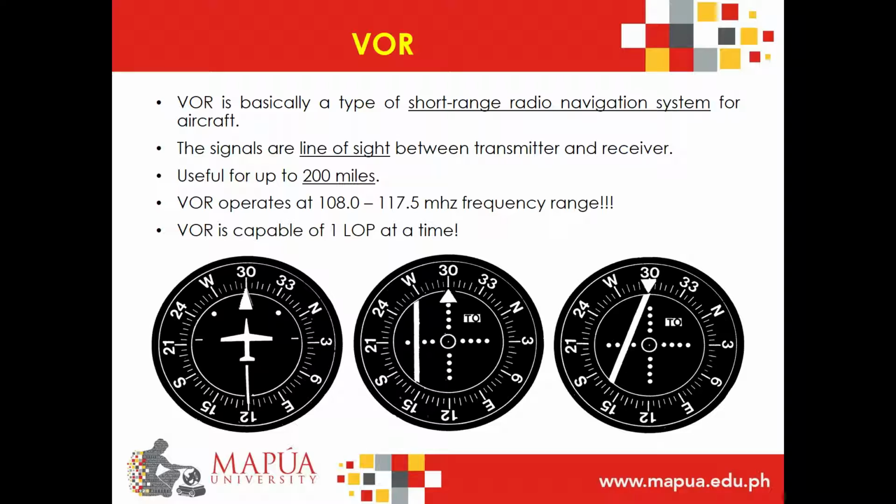The first 4 MHz is shared with the Instrument Landing System, or the ILS band. To leave channels for ILS in the range 108 MHz to 111.95 MHz, the 100 kHz digit is always even. So 108, 108.05, 108.20, and 108.25 and so on are VOR frequencies, but 108.1, 108.15, 108.30, 108.35 and so on are reserved for the ILS in the US.